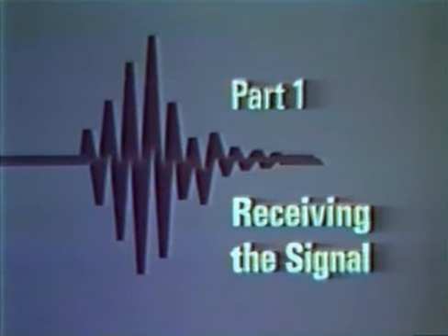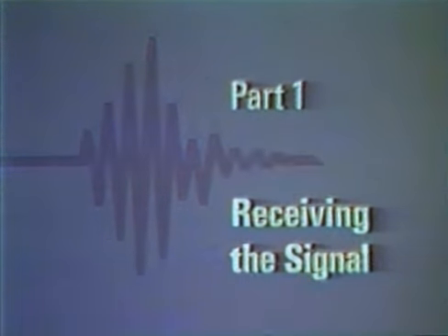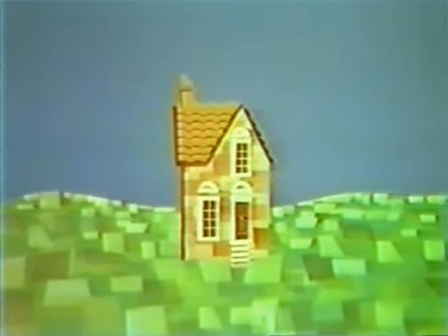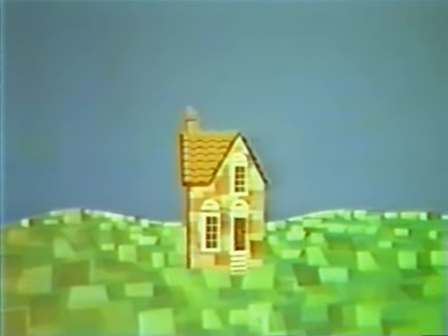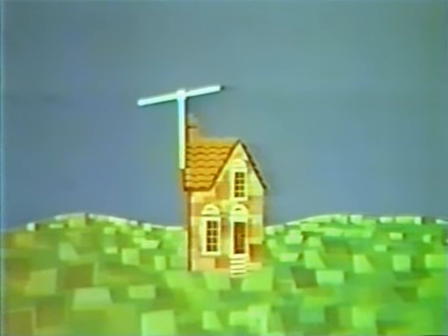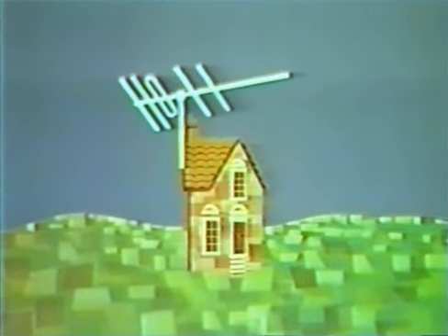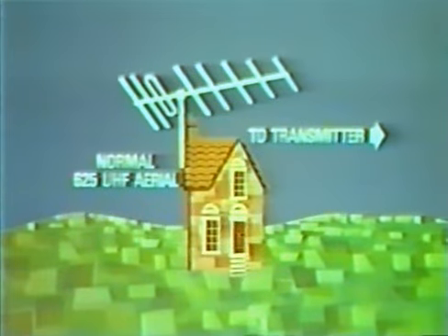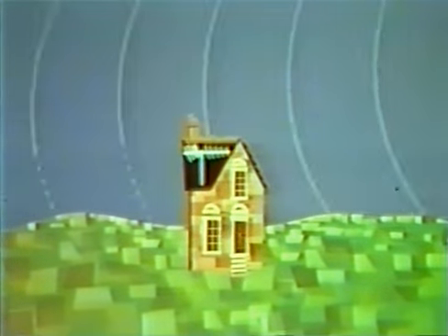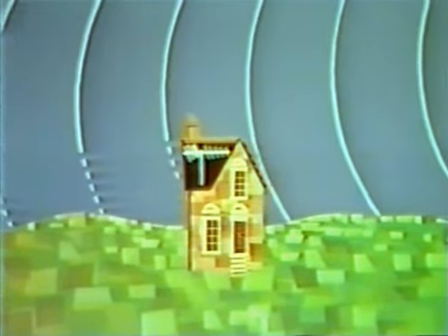Part 1 deals with signal reception. No matter how good a receiver may be, it cannot show a good picture unless it is provided with a good signal. This usually demands an efficient outside aerial with a low-loss coaxial. A loft aerial clear of metal objects may, however, be satisfactory in strong signal areas.